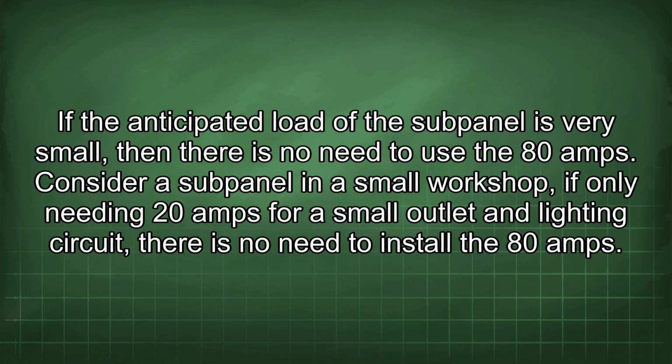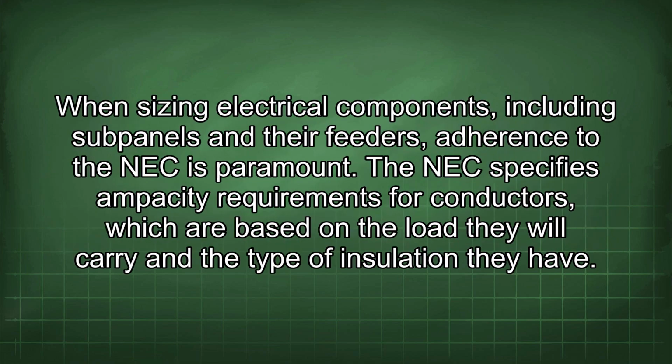Consider a subpanel in a small workshop. If only needing 20 amps for small outlet and lighting circuits, there is no need to install the 80 amps. When sizing electrical components, including subpanels and their feeders, adherence to the NEC is paramount.